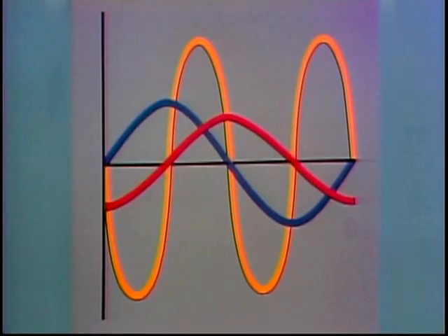Reactive power is the kind of power that you would find in a purely inductive circuit or a purely capacitive circuit. It doesn't do any useful work. Let's look first at an inductive circuit and then a capacitive circuit, and you'll see what I mean. For an inductive circuit, like the ones we saw in segment 2, we get voltage and current sine waves that look like this. Voltage and current are out of phase. Current lags behind voltage.